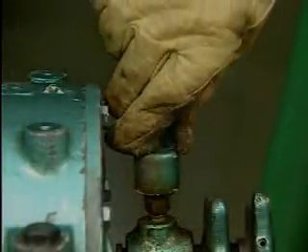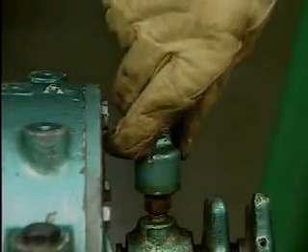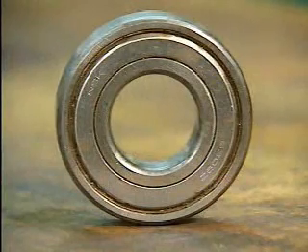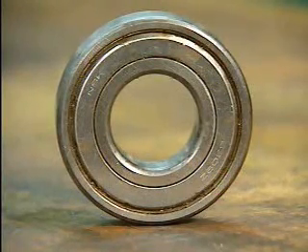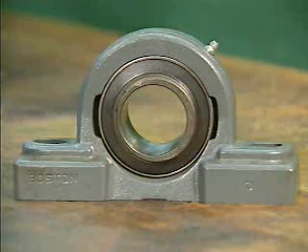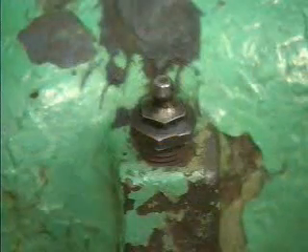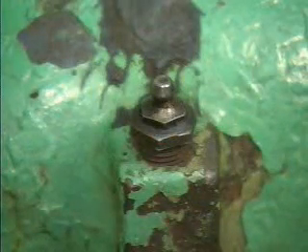These methods are used only with bearings that are not sealed. Sealed bearings are permanently lubricated and they do not have to be greased. Many bearings that have to be greased are contained in housings that have grease fittings. A grease fitting is a small rounded projection on the housing that has a hole in it.